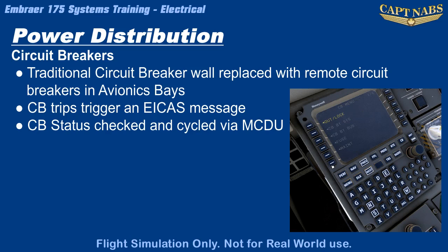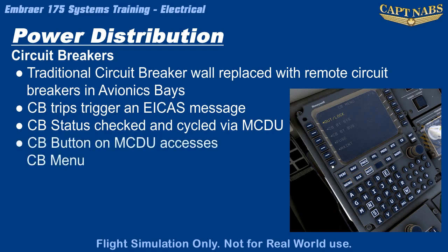Not only is it easier to monitor and control a large number of circuits without even getting up from the pilot seat, but finding the needed breakers is much easier as the circuit breaker menus in the MCDU are sorted by system. The system is accessed by using the CB button on the MCDU. This button brings the pilot to the CB menu.